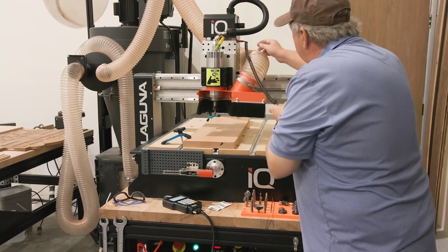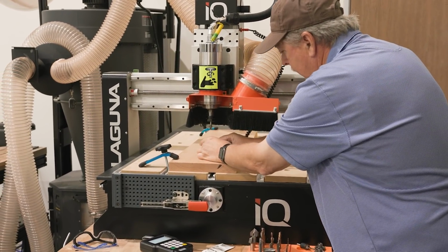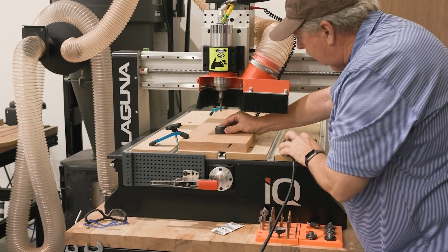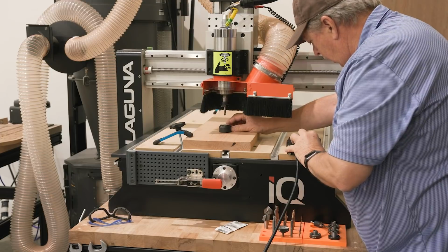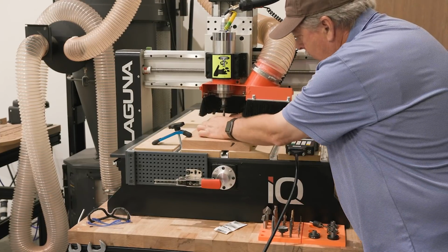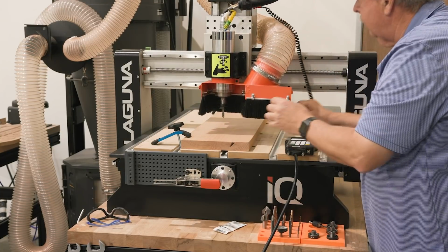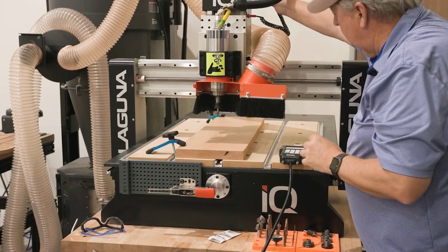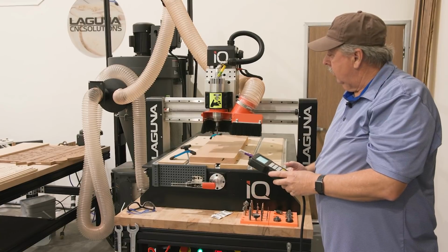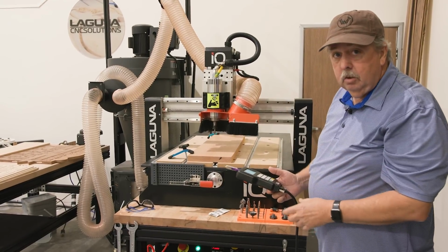Recall that we always want to check this plug to make sure that it's in properly. Move it down close to the Z, and then hit Menu, On button together, and it will cause it to zero out. So now we set the Z0, and we're ready to select the program to cut. After, of course, we put on the safety glasses and turn on the dust collector.